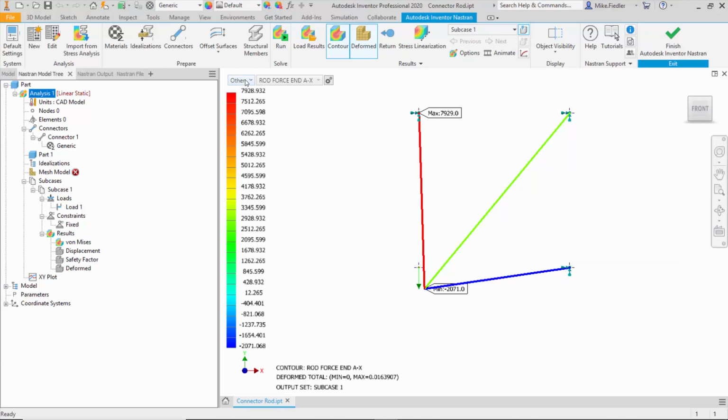And then finally, to check our stresses, we go to stress, and we can interrogate. Vertical member should be 3965, and there you see 3964.66, so again rounding. Diagonal member should be 1465, and there we see 1464.5, and the horizontal member should be 1036, and there we see, again, rounded up to 1036.